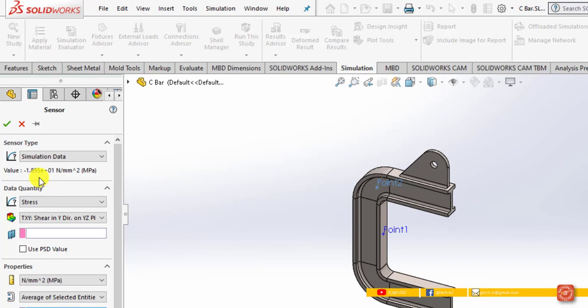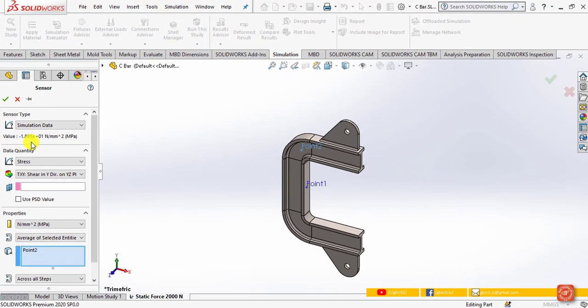You can also note that the z component sigma z, shear stress in yz and shear stress in zx direction are all zeros. It is called a plane stress state, and the stress states discussed in this lecture are all plane stress states.